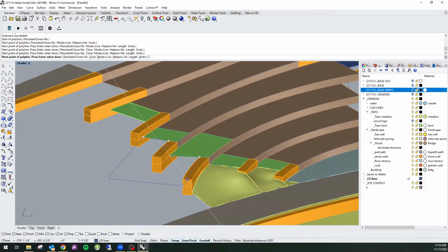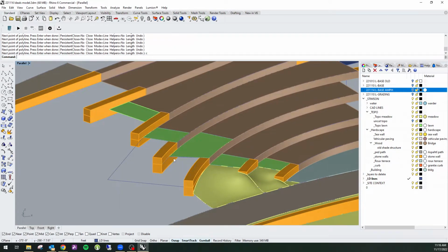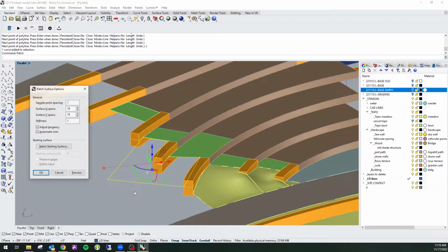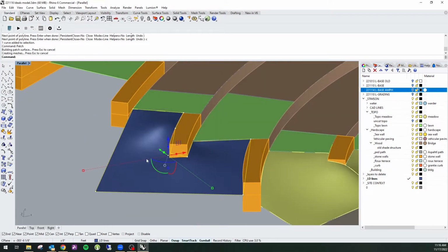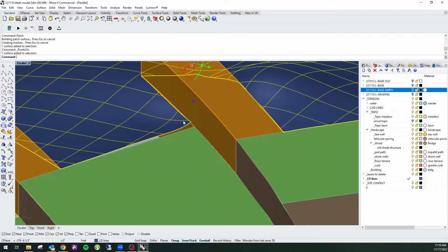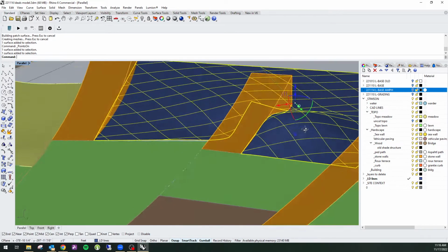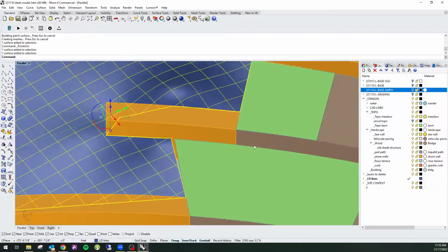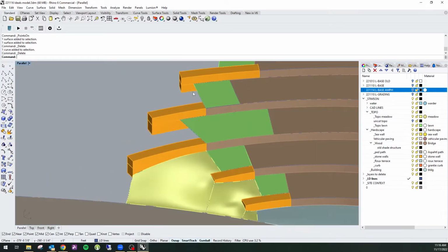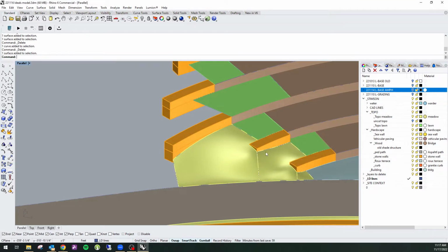You can't just draw in, say, this is what I want my patch surface to be, and draw this around every terrace. If you try to patch this, it'll still think of this as just one surface, and it'll just try to interpolate through this crack here. And the bottom surface is always going to curve upwards, and it's never going to match perfectly. The top surface is going to curve downwards. So what you really need to do is have an individual surface for every level like that.